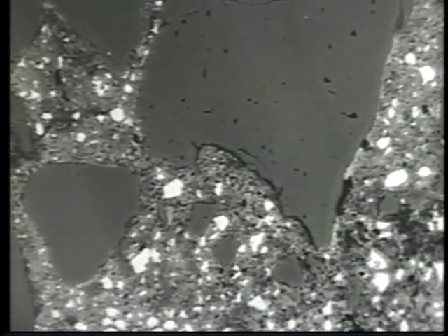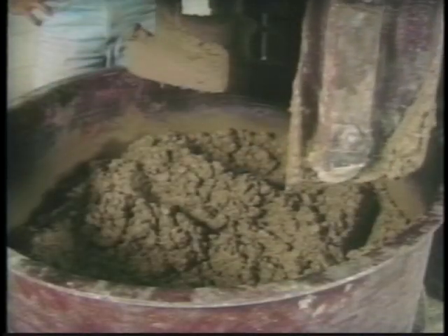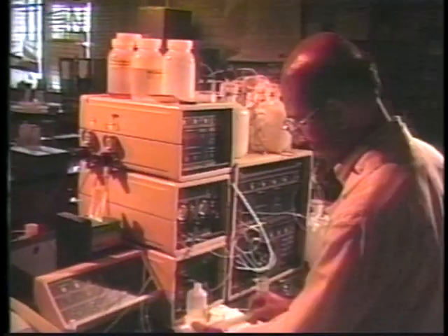We have seen how concrete is a random composite with a complex microstructure over length scales ranging from meters down to nanometers. At every length scale, percolation and composite ideas can be used to describe the microstructure. Our understanding of microstructure is the key to controlling and improving the properties of concrete.